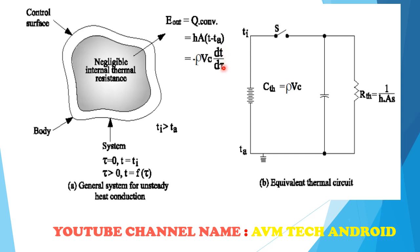So the figure A, that is the general system for unsteady state heat conduction, is very much clear to you, where T is any temperature when time is more than 0, Ta is the atmospheric air temperature, rho is the density of this solid material, V is the volume of this material, c is the specific heat of this material, and dT by d tau is the variation of temperature with reference to time.